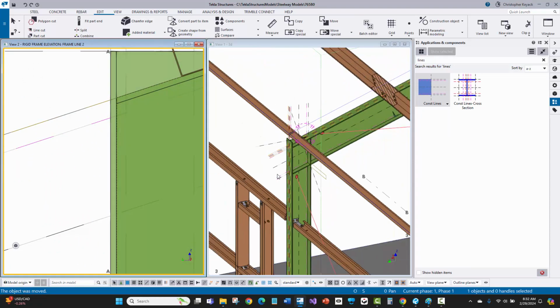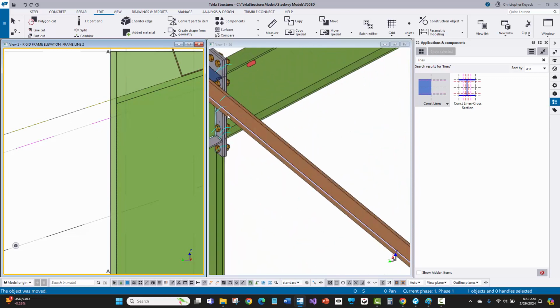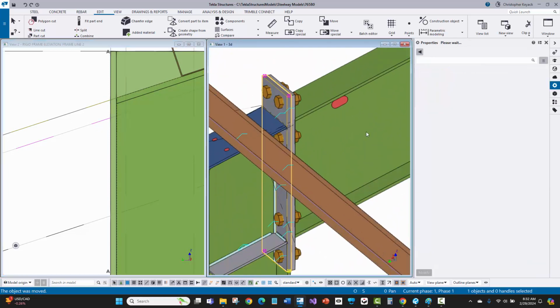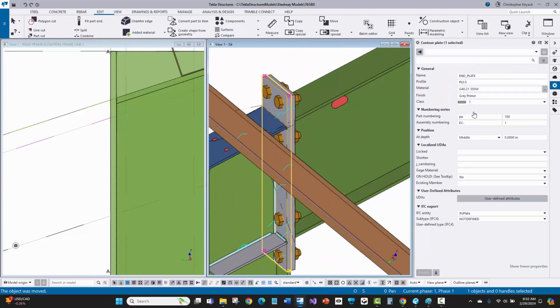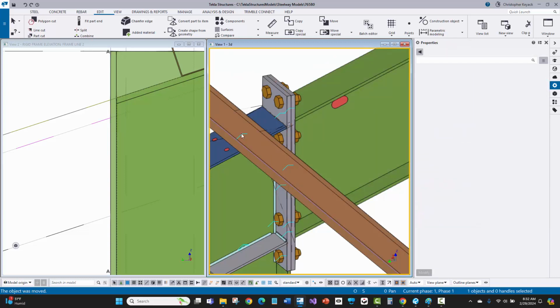Now to get an existing end plate's properties, so I don't know your standards fully well, so let's just see what's here. So I can just grab an existing plate as a starting point, and then I could save those settings away. And I kind of did that here as end plate and rafter, just so that way I can make sure that I'm matching exactly what SlideRule did, and I have all the same matching standards here that your cleanup tool does. So I can start with that and save it away, but I've already kind of done that here.